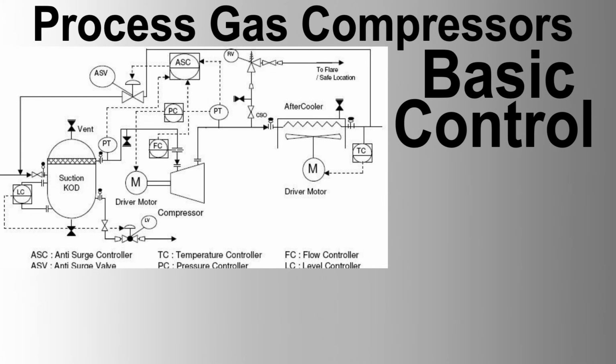Implementation steps. Step 1. Evaluate the existing system's capacity and control architecture. Assess the current load, control loops, and instrumentation. Identify points of integration for the new compressor. Step 2. Design the control strategy and loop configuration. Develop a master-slave or load-sharing control strategy. Design the loop configuration for suction, discharge, and anti-surge control.